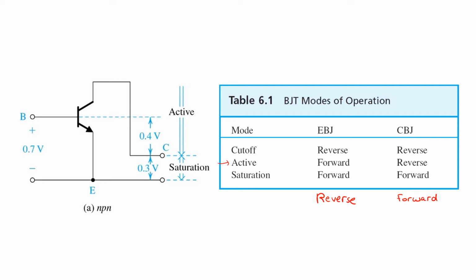This can in fact happen, but remember that unlike a MOSFET, a BJT is not physically symmetric. The emitter is designed to have a much stronger carrier concentration than the base to ensure that its majority carriers far outweigh the majority carriers injected from the base into the emitter. And that's what helps ensure that the base current is only a very small fraction of the emitter current.